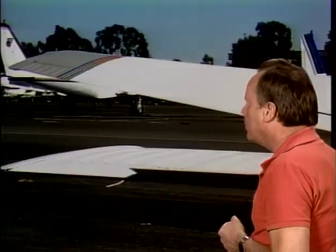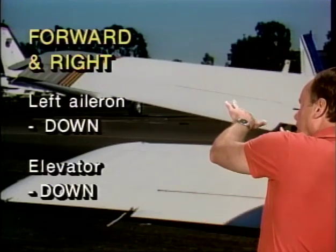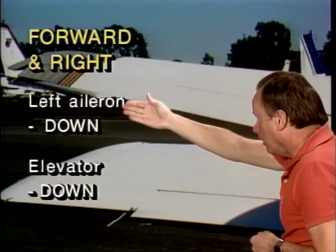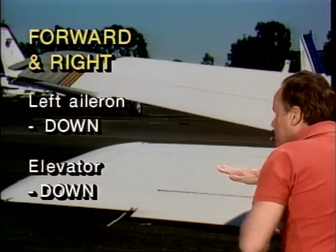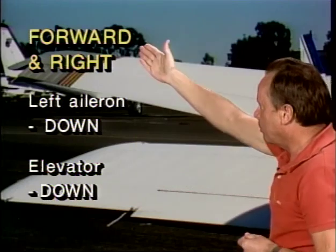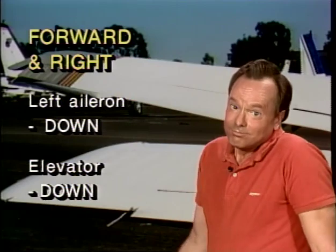Now, you might guess, will they ask you anything else about this? Yes, they're going to ask you what happens if you move the wheel forward and to the right. So here we are moving the wheel forward and to the right. When we do that, we're trying to turn the aircraft to the right, so this left aileron will go down. We're pushing forward on the wheel. We want to go nose down, so the elevator will go down. So if you move the wheel forward and to the right, the left aileron will go down and the elevator will go down. The FAA figures that's a good idea for you to know, so when you hook up these controls, you do them right.